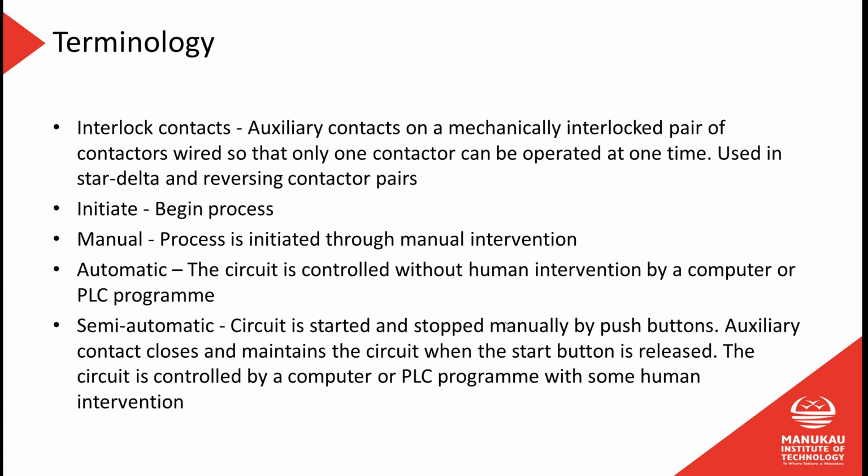1. If we think about what a normally closed contact is, that means when my coil on contactor 1 is energized, the normally closed contact will be open. When my coil is de-energized, then that contact will close. So if coil 1 is energized and contactor 1 is on, that normally closed contact will open.